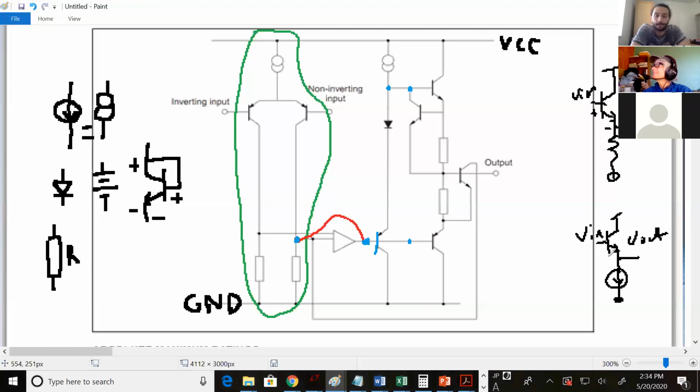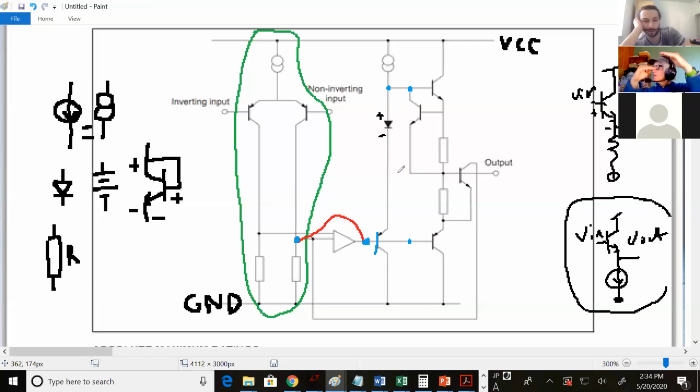Okay. All right. So yes, this right here is this circuit right here, but flipped. And you get to ignore this, it's just a battery. It's just putting a VBE drop across there. That's a DC voltage. So both sides of that diode are moving together, and it's like it's not there.